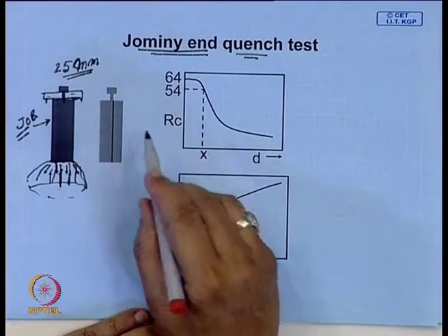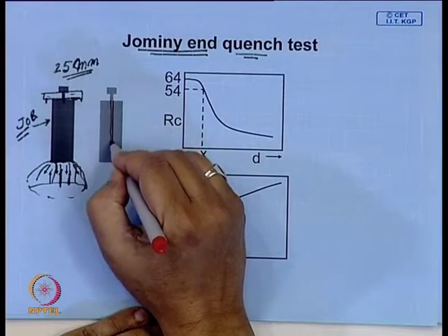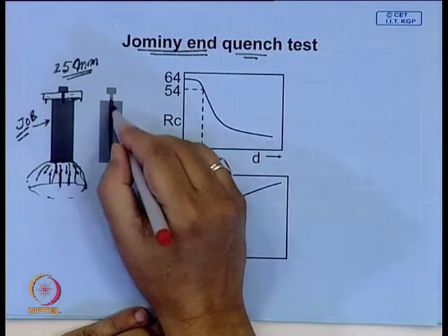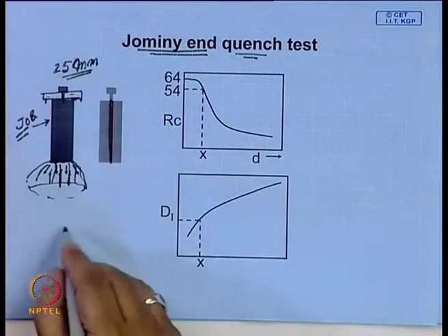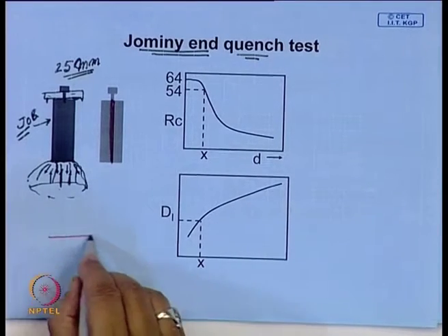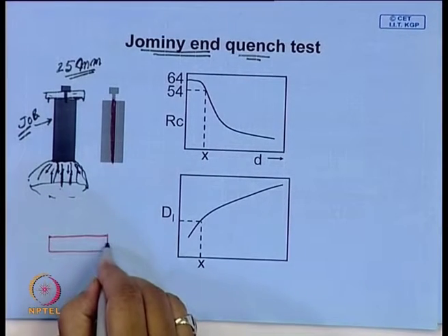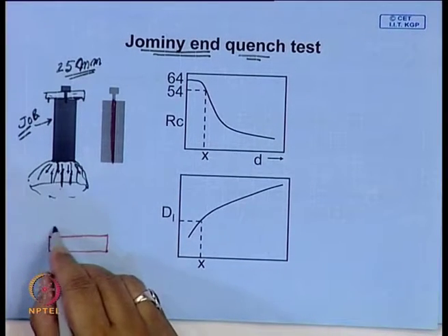After it has been cooled to room temperature, take out the sample, and polish and grind a small portion here. This is a cylindrical piece. Now, what you do, you place this in a Rockwell hardness testing machine, with an indenter, and there are also devices with which you start measuring hardness.